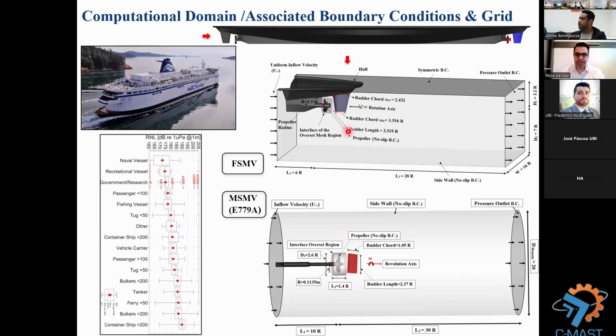For the computational domain, it's very important first to prevent the blockage ratio, and then the size must be enough to capture the wake structure generated by the propeller. And you can also see here the boundary conditions we consider for our modeling.